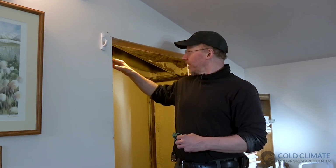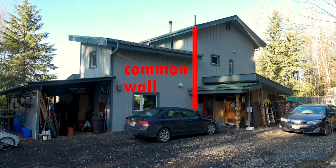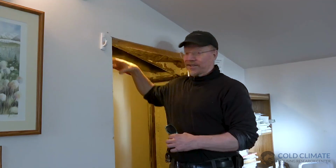We are now in the master bedroom. I'm standing next to the master bedroom closet, and this is where the recurring problem has been taking place every winter for years. And the issue we suspect is the common wall where the new house wall was attached to the old house wall, and the moisture has been coming down through the closet ceiling. And we're going to conduct a series of tests to determine if that's truly the case, and if we do have an air leakage between the new structure and the old structure.